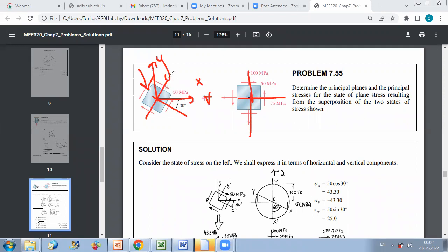To do this, you can use, of course, the Mohr circle. If you consider the following figure, what do you know? You have only shear stresses. You don't have normal stresses. So this means that you are in the case of pure shear.